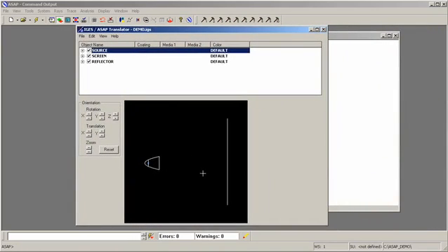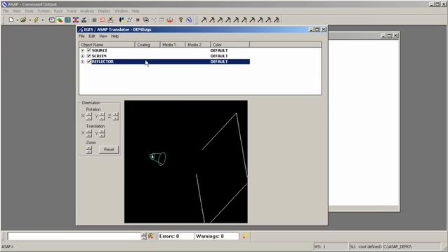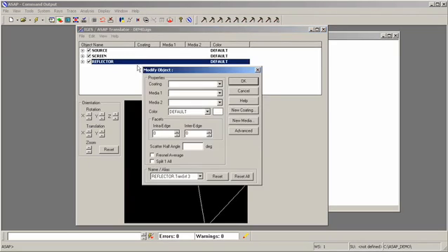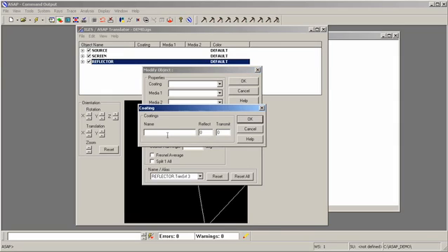And down at the bottom here we have a very simple graphic that helps the user identify objects when we assign optical properties. In this case, we will assign optical properties to the reflector. The way we do that is we highlight the reflector layer here, right click, modify, and if we want to define a new coating, for instance, click on the new coating button, assign a name, ref_b. Over here we have the reflection and transmission coefficients. We'll assign a reflectivity of 0.95 and a transmissivity of 0. So our absorption is going to be 5%.